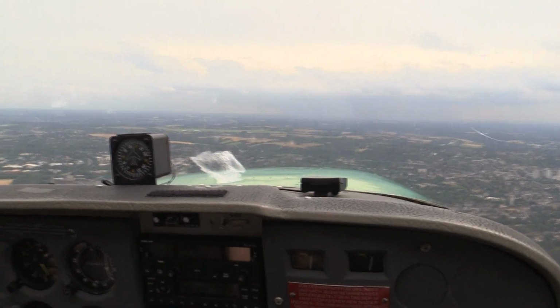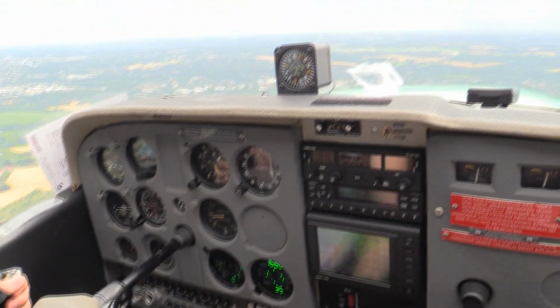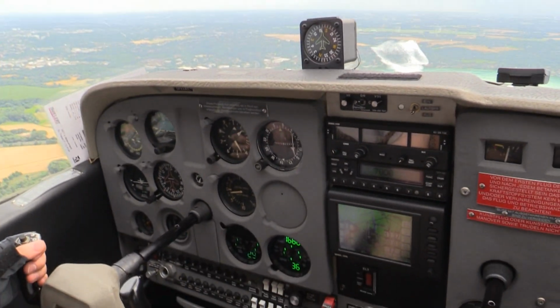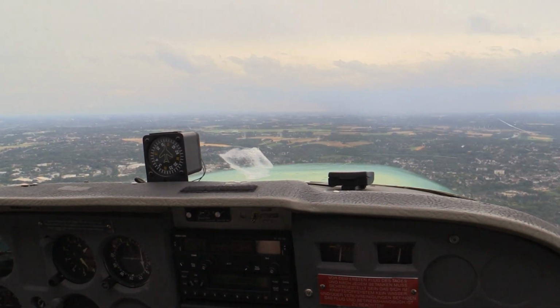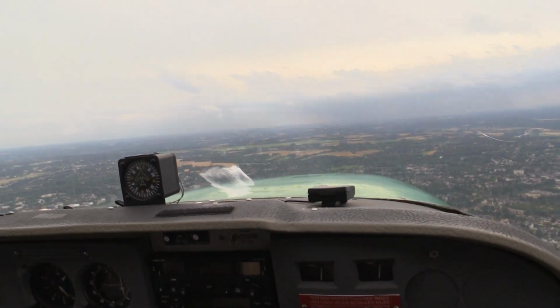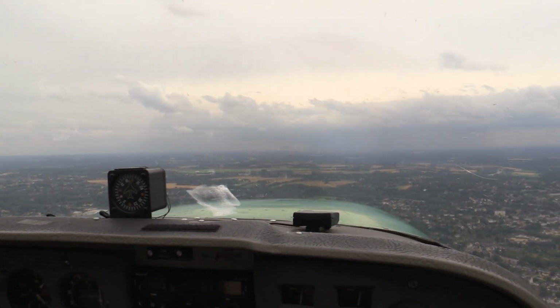But we're now at 1,500 feet, descending down to 1,400 feet for the traffic pattern altitude, and we're just about 1 or 2 minutes off to the traffic pattern of Essen. And we also reduced our speed a little bit into the wide arc, so as soon as we establish the end of the downwind, we can expand our flaps and start with our landing configuration.